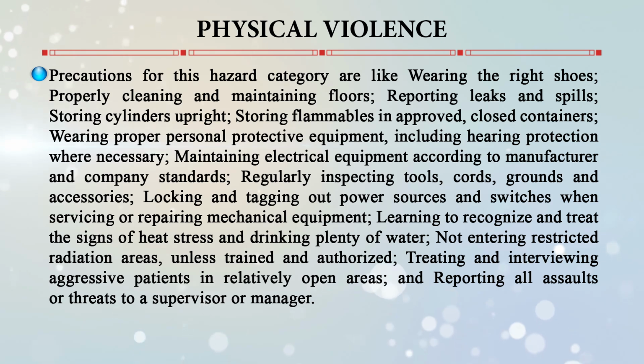locking and tagging out the power sources and switches when servicing or repairing mechanical equipment is going on, and learning to recognize and treat the signs of heat stress, drinking plenty of water, and not entering restricted radiation areas unless trained and authorized. So these are the most important things one has to remember.